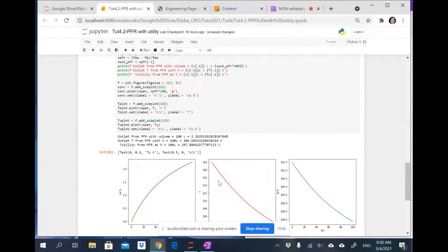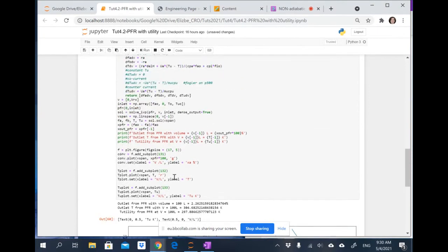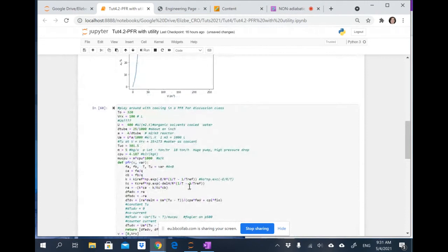This was quite quick to find after playing around with it for a bit yesterday afternoon. But let's see what we have achieved. Not much. We haven't achieved much because we still have a very small conversion in our reactor. So what I am now going to do, this is just illustrating the variables. Listen, let's just pause with this U value. I cannot just change the U value and say, oh, but I want better heat transfer, or I want poorer heat transfer. So I am going to vary this until I've got the heat transfer that I desire.